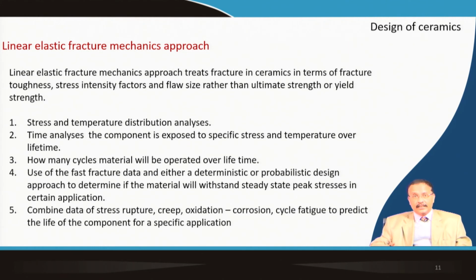The fast fracture data, either deterministic or from the probabilistic design approach, is used to determine if the material will withstand the steady state peak stress in a certain application, which is much more global in nature. Combined data of stress rupture, creep, oxidation, corrosion and cyclic failure is also used to predict the lifetime of the component for a specific application.